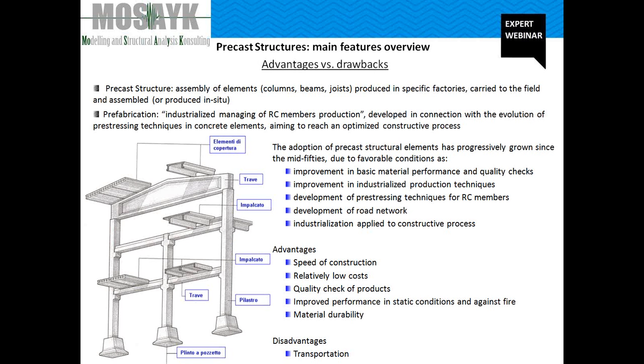The success of the prefabrication technique in Italy mainly depends on the speed of construction and the relatively low cost. So it is quite understandable that the method of emulation of cast-in-place concrete, envisaged by the modern design codes of the main seismic-prone countries, never had particular success in the Italian context in past years, because it mainly results in a partial increase in site labor and longer construction time.